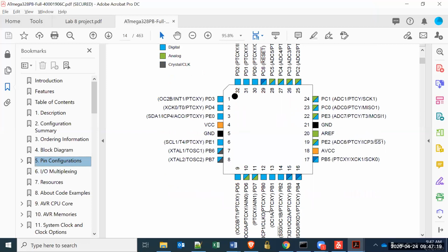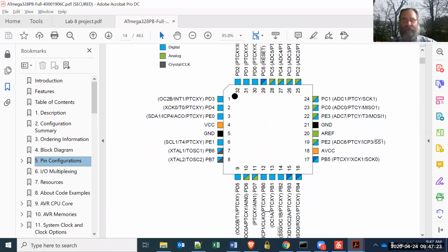So we're supposed to be using UART1, right? No, UART0. UART0? Because it's the only one connected to the computer. And that's why it's not playing nice with the 7 seg. Yep. Huh. This is a pickle.